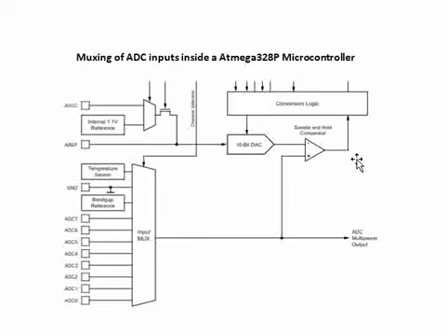And then another important point we have to remember is, for the ADC to work in any scenario, any microcontroller or anything, the important point is the reference.